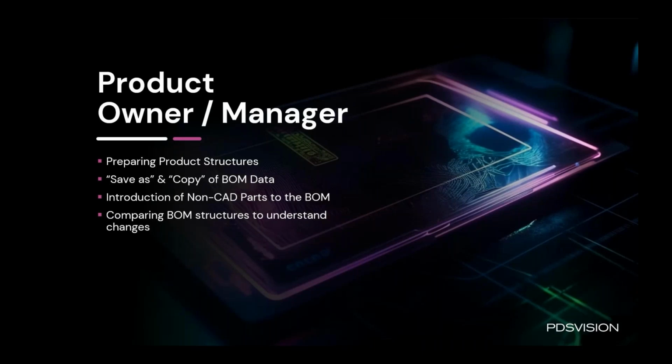We also saw Pat introduce some non-CAD elements into the bill of materials, like the software element that we saw, as well as leveraging BOM comparison tools to understand the differences between the part structure and the CAD structure. You can also use these BOM comparison tools to identify differences between versions of structures as well. So maybe you want to compare the as-released version to the current version of the product structure. You can leverage the similar sort of UI for investigating those changes.